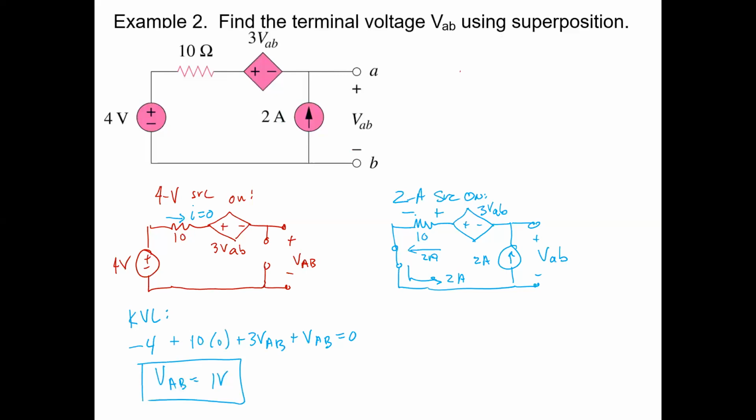When I turn off the voltage source, it's still connected, but when I turn off the current source, it's disconnected. My notation in the circuit symbol, right? Yeah, that is intentional. That's because when you turn off a voltage source, the voltage goes to 0. And the way we model a 0 voltage drop is by putting a wire across 2 terminals, because when you have a conductor there, they have to be at the same potential. So the voltage difference between these 2 terminals is 0 volts, and that's what we get when you turn off a voltage source.